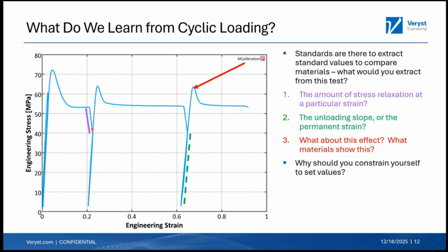I know that the stress is going to reduce 20% after it's gotten past its yield point. I get a lot of information about how much of this response is plastic behavior and permanent deformation, and how much of it might be recoverable. We also get information about the unloading slope. The unloading slope for polymers like this doesn't always match the loading slope that you have here. So being able to capture that can be helpful if you have multiple loadings of your material.